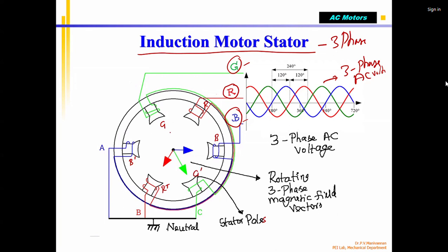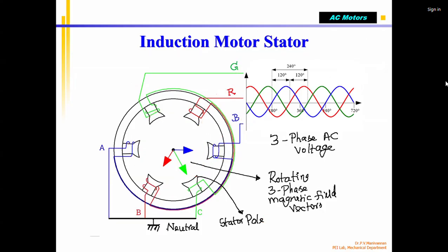So together this plus this is called one magnetic pole pair, and this is another pole pair, and this is another pole pair. So there are six poles. Diagonally opposite poles are wound with the same coil. Correct. Three-phase coil. One is the red coil. You can see the red is the input voltage. I'm giving this input voltage. Current flows through this coil, through this fold, then comes like this, and enters here, and goes to neutral.